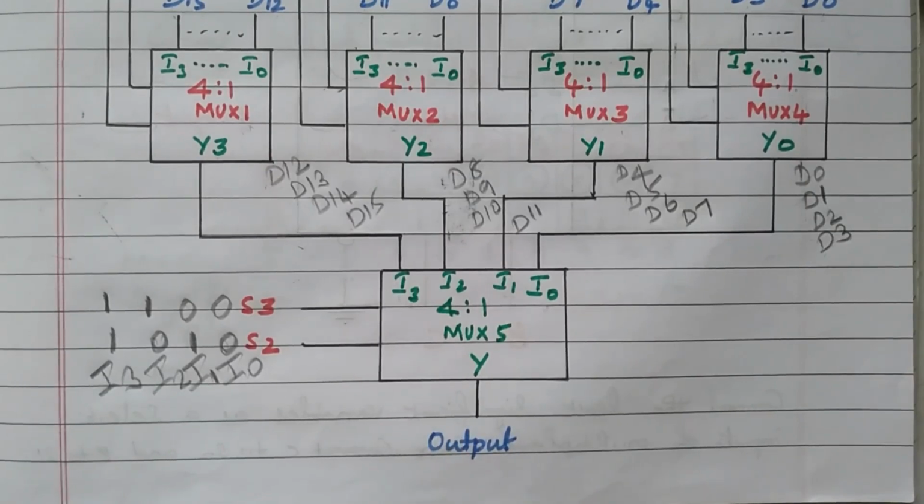So in this video we discussed how to design a 16:1 multiplexer using 4:1 multiplexers. We discussed how to connect the selection lines. How many multiplexers are needed? There are 4 multiplexers needed to connect 16 data. In order to streamline these 4 multiplexers, we need one more multiplexer. So the 5th multiplexer finally produces a single output, right? The 2 selection lines are connected parallelly to all 4 multiplexers. Another 2 selection lines are connected to the 5th multiplexer, so that we got a single output.